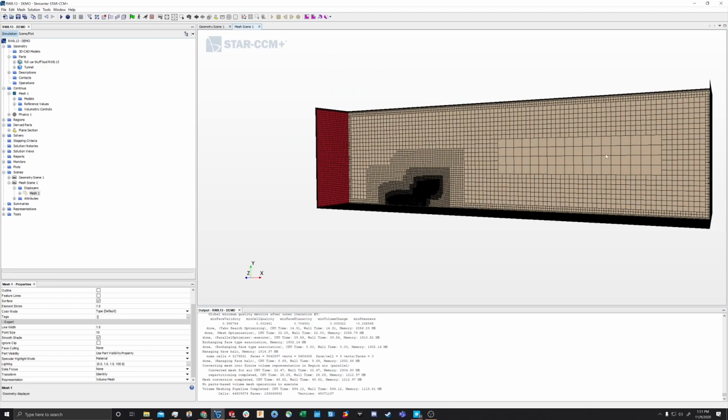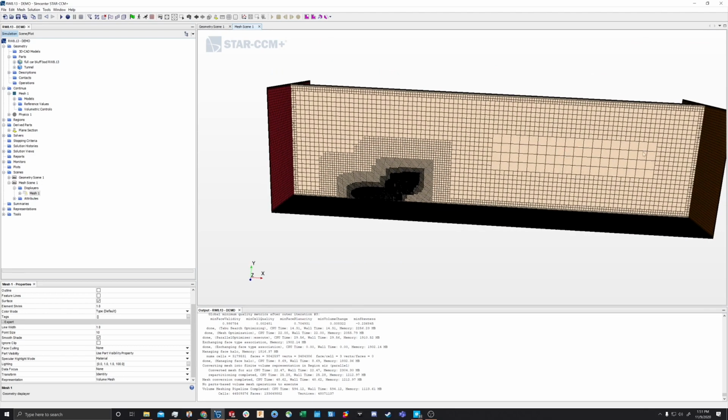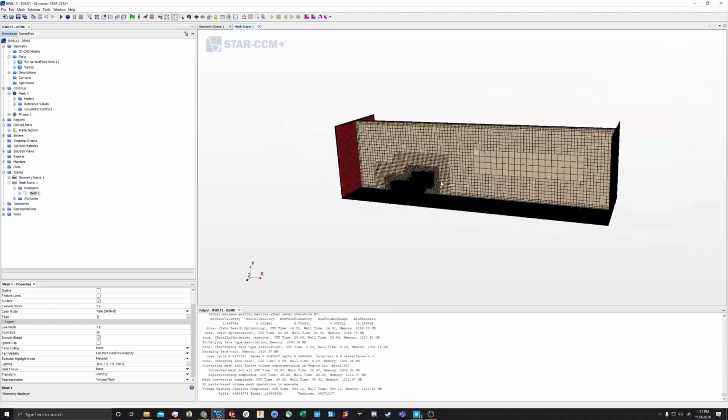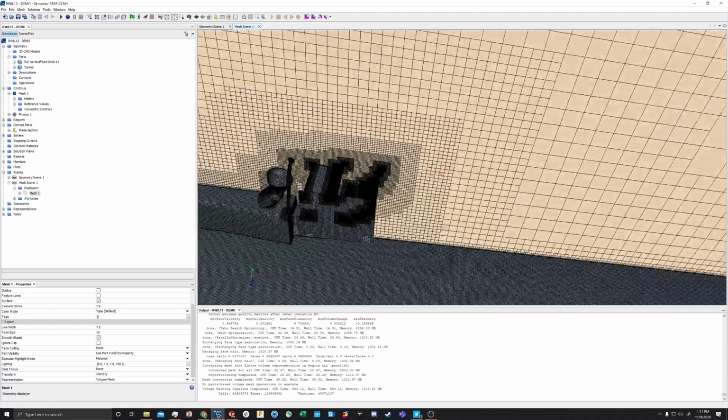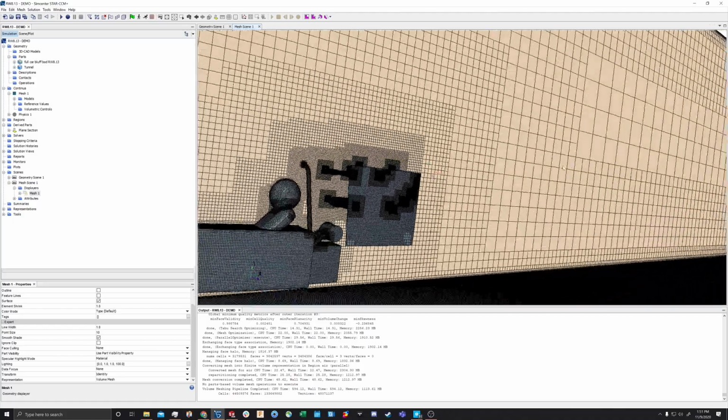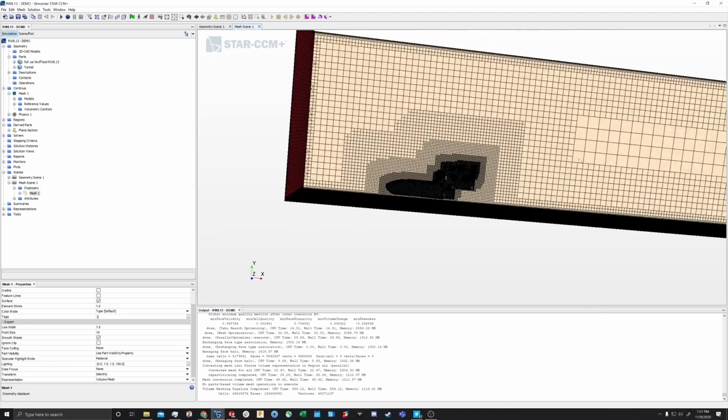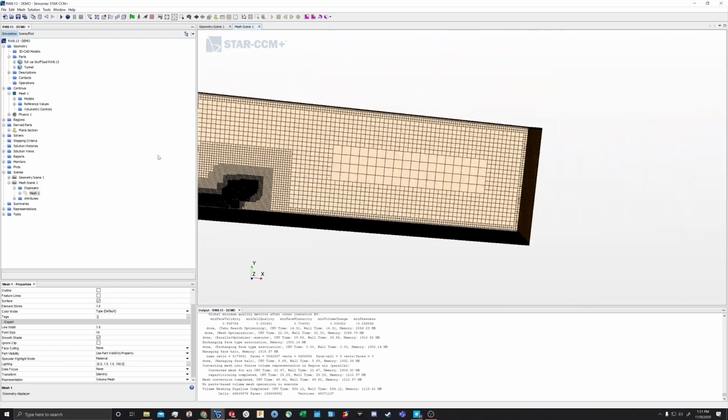It gets pretty big. So like back here, this is pretty big. This is a maximum size that those squares will get, and they'll run much quicker, which helps. You want this sim to be fast, especially something simple like this. We don't want to invest 9 hours of compute time to run this, so having a simpler mesh back here can help with that.